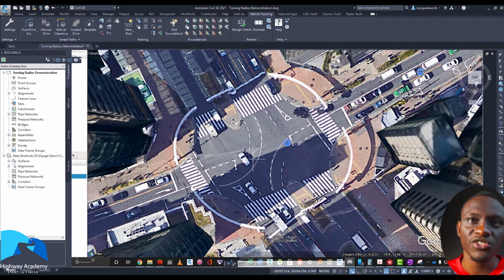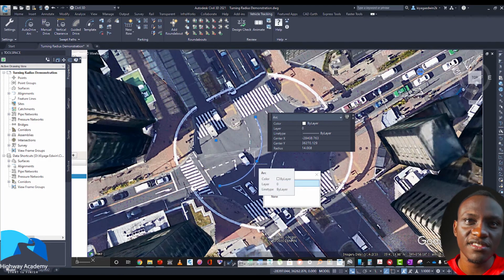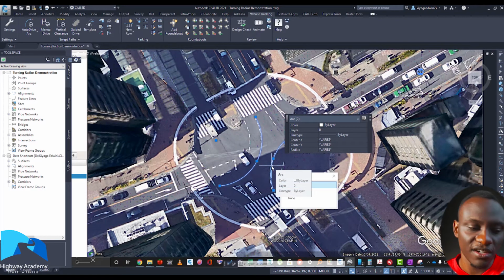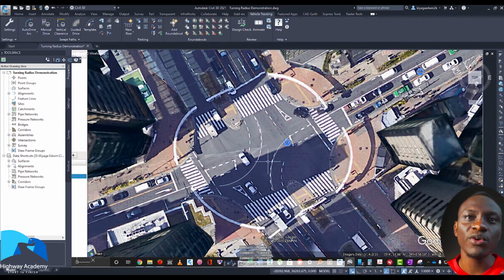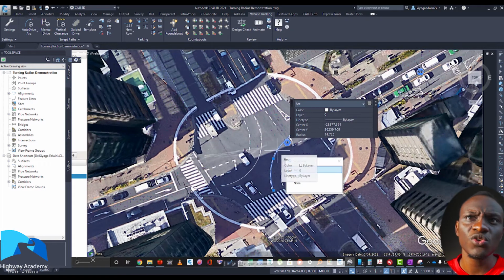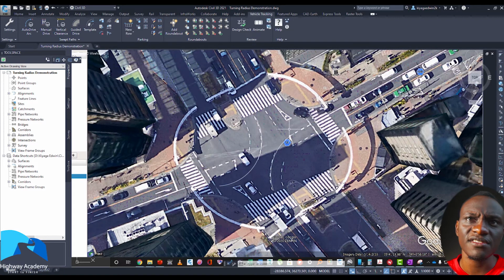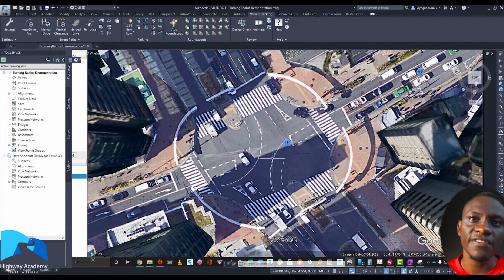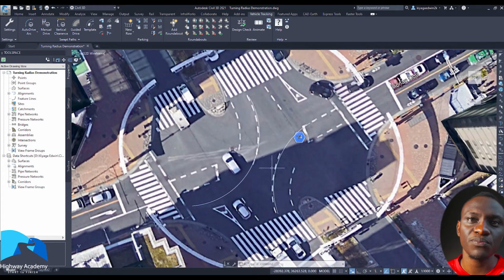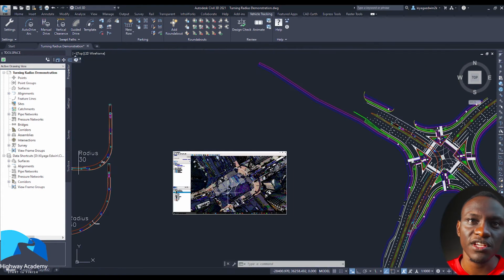What I'm showing here is a junction in Japan, I think at Kishishi. We're showing a steep turning radius of 14 meters, and then another of 14.7 meters. Earlier we showed that the curb turning radius of the design vehicles we're using is 13.67. So in Japan they're designing the outer radius as 14 meters because they've mostly catered for the biggest turning radius. You'll find there's an offset between the two turning radii. It's very important for safety reasons to make sure the two turning radii don't meet.